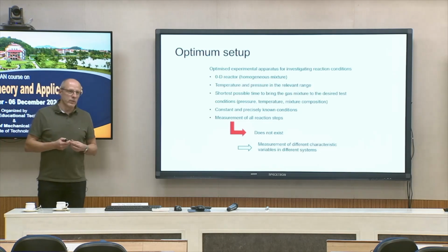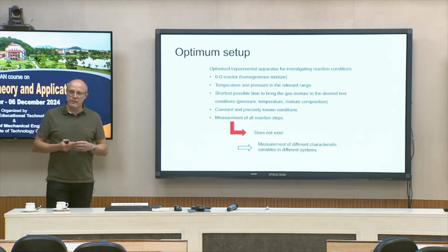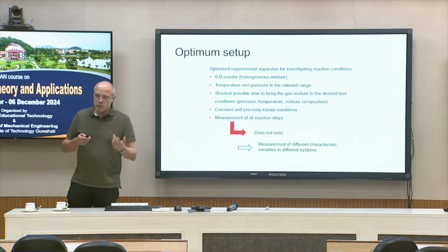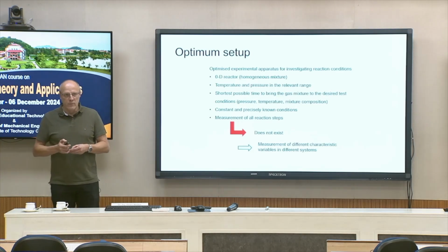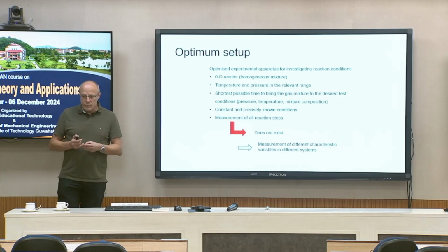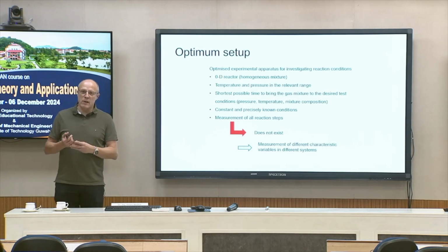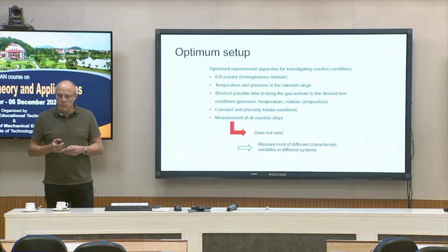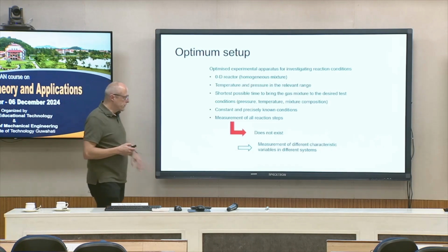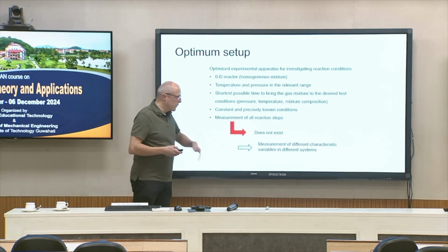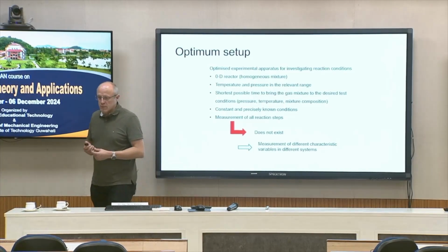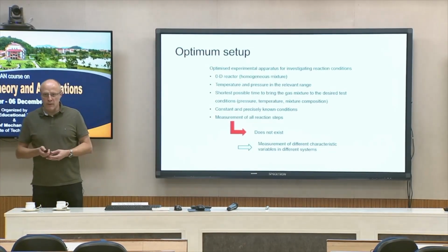The reactor should be perfect in a way that we have a homogeneous condition, so there is no disturbance by vortices, by cooling effects or whatever. And it would be nice to measure all reaction steps we are interested in. Of course, this does not exist, so we have to use different systems for different characteristic variables.